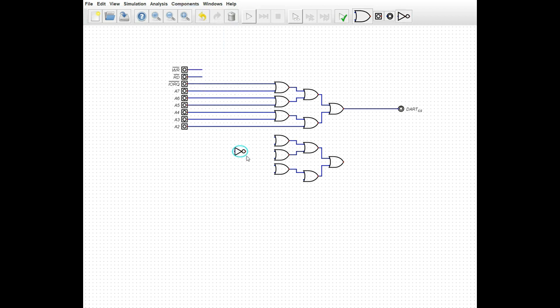Now if you were using an actual IC, just discrete logic, let's say that this is IO request, bits 7, 6, 5, and 4. This bit is going to need to be high, which means that in this circuit we're going to have to convert it to a low when it's high. So typically what you would do is you would NOT this.